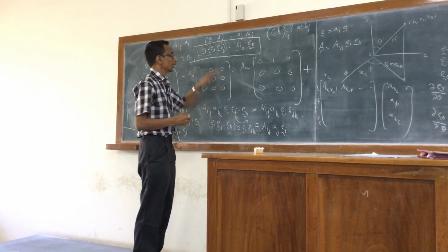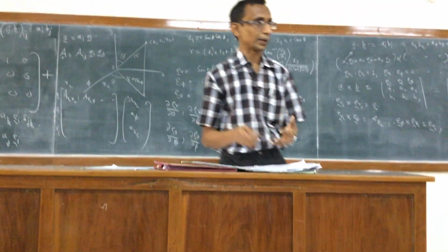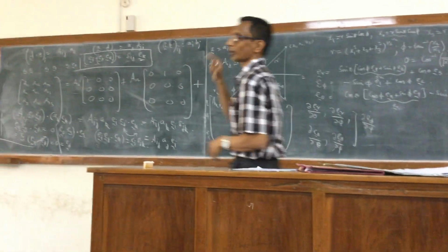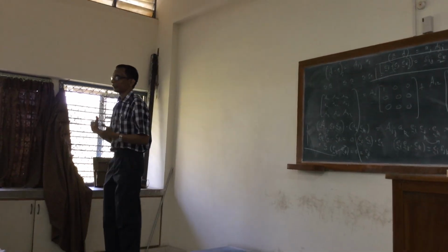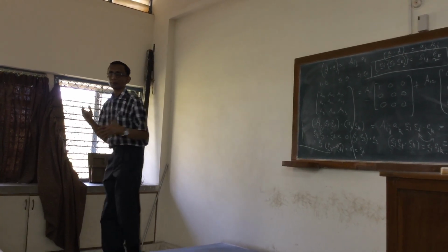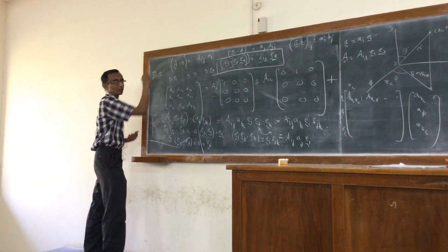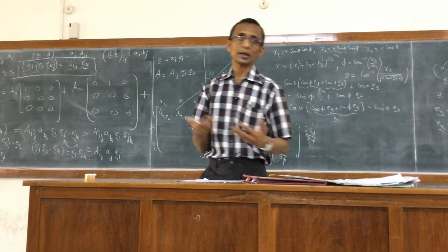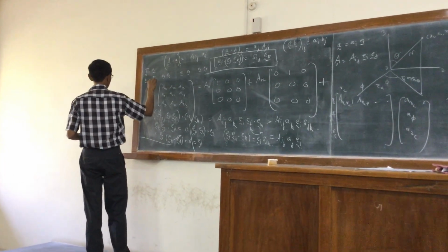Right? So the same principle will apply to the cylindrical coordinate, primarily on account of being an orthonormal basis set. So all of these operations will carry over, right? And whatever you did in the rectilinear coordinates, you will simply do in the cylindrical coordinate. So something like this we require when you want to calculate the stress vector, for instance, right? You have to take the normal of T dot N or N dot T, both are the same for us because the stress tensor is symmetric.